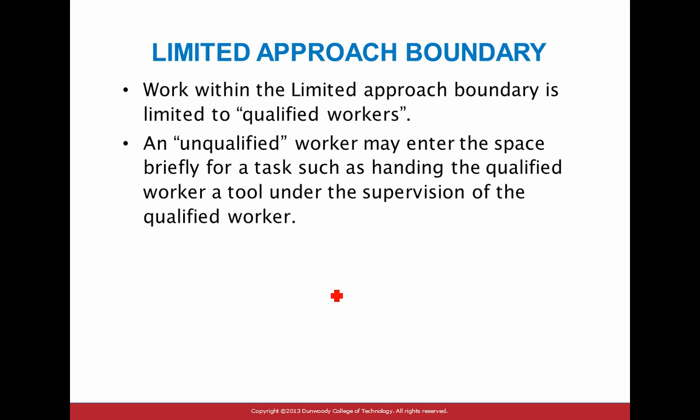Okay, so limited approach. Like we talked about, only qualified people can get into the limited approach. An unqualified person may enter the space briefly for a task such as handling the tools. I'm working on a piece of equipment and you're helping me.